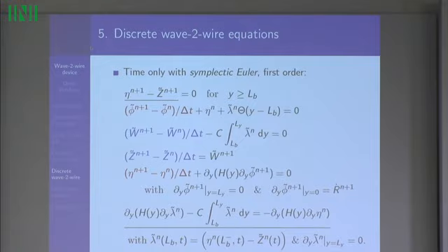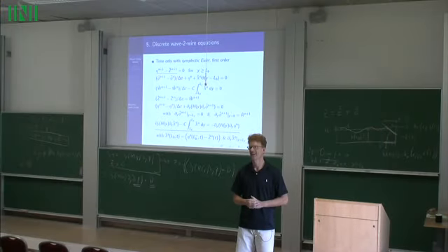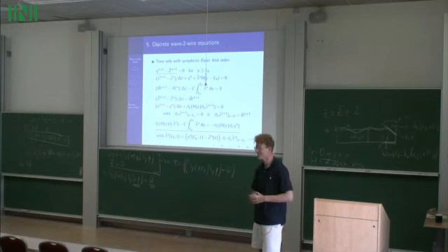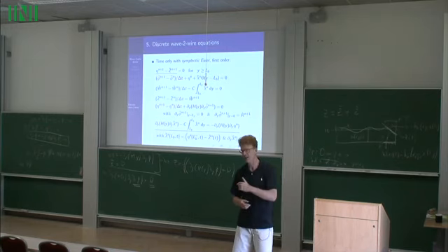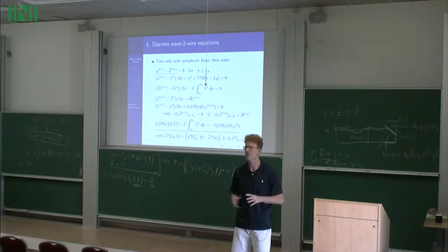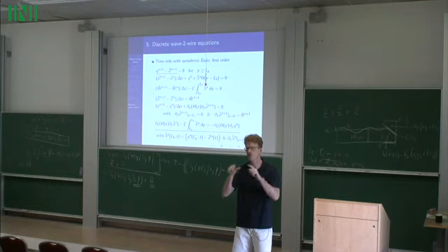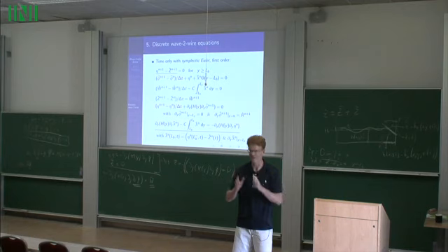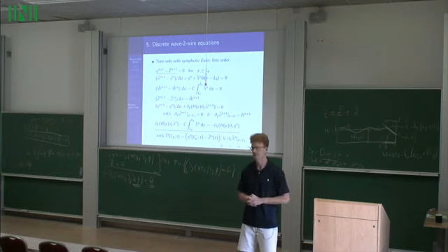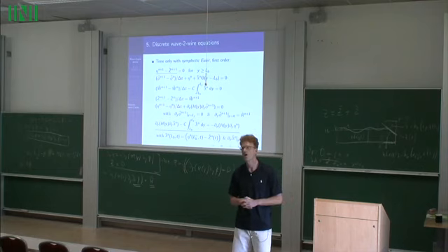I have one, but it's for a steady case, and then the flow in and out of the domain. So we could use that, but it requires a slight adaptation. So we use just 3 meshes to do that. So the Richardson or Aitken, in case you don't have an exact solution. Otherwise, if you have a really fine solution, at least you can see the effect of your trick, the local error.